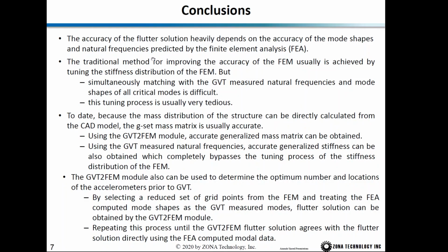The traditional method for improving the accuracy of the finite element result is usually achieved by tuning the stiffness distribution of the finite element model, but simultaneously matching the GVT measured natural frequencies and the mode shapes for all the critical modes is difficult. This tuning process is usually very tedious.